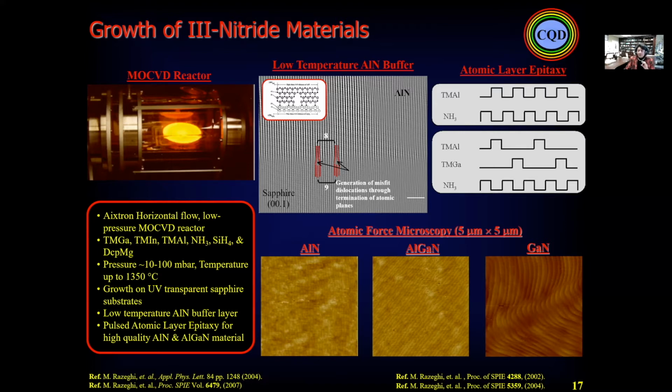I want to show you only one thing here. We have a sapphire substrate, and we are growing aluminum nitride on the sapphire substrate. First of all, you have to know that for any material that you are growing, the growth temperature has to be at least 2/3 of the melting point of the crystal. So here the growth has to be at least at 1000 degrees. Every 9 planes of the sapphire correspond to 8 planes of aluminum nitride. But as you can see, every 9 planes, I have 1 edge dislocation, and after that there is no defect. So that is the perfection.